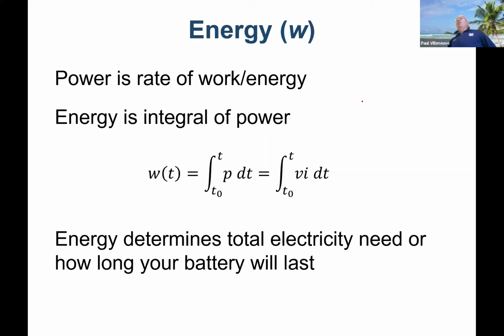Batteries also have something called cold cranking amps. That's not as useful. That just tells you what the battery is able to deliver under sort of short circuit conditions, if you will. If it's a cold battery, the resistance gets to be a lot higher in a battery. So how much current can it possibly provide to start up a fairly big load? But the most important thing is amp hours, right?